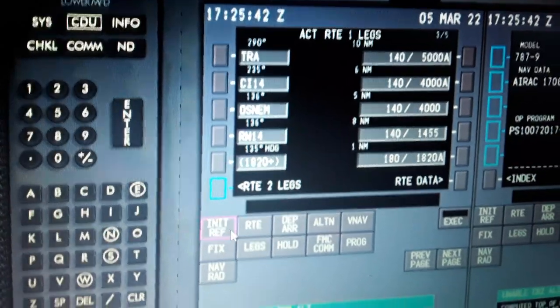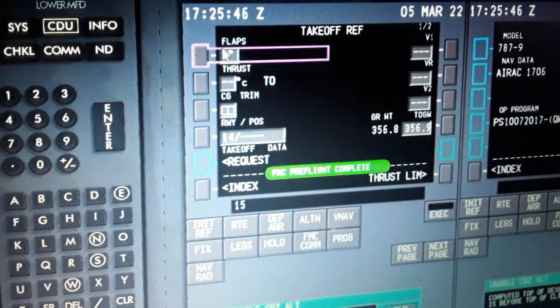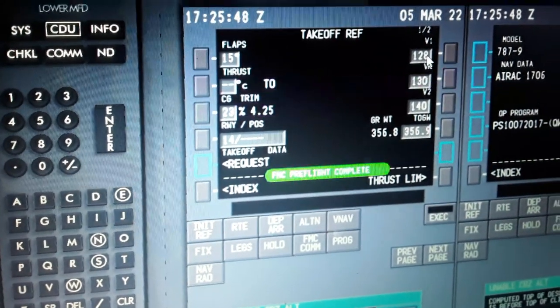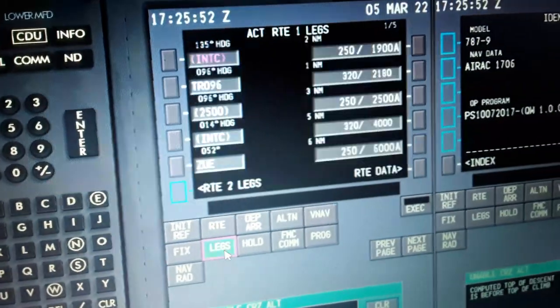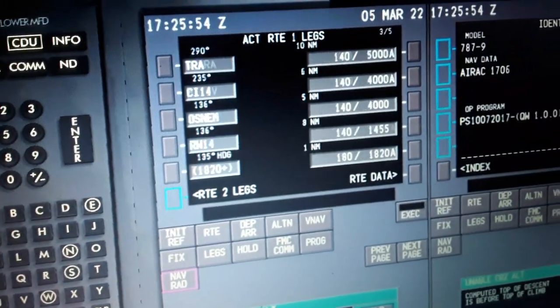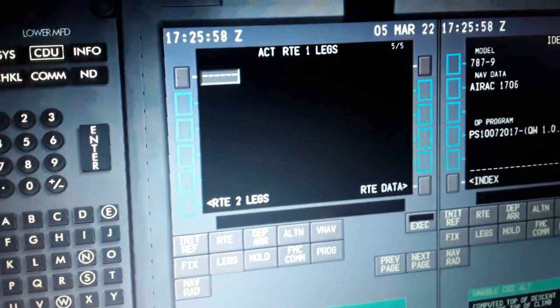from Osnem, 140 knots. So we use the flaps for approach and landing over here, center of gravity, and the takeoff speed V1, we rotate V2 for this center of gravity. So we have a complete flight plan over here, the legs are created.